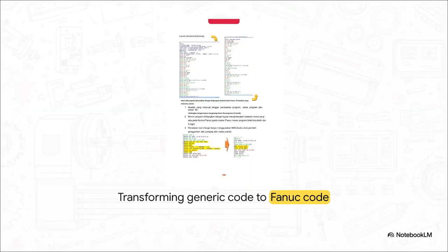Let's actually look at this in practice. First, take a look at the raw, generic output straight from Mastercam's post-processor. It is cluttered. You've got parenthetical comments, ridiculously long file names, and descriptive tool data that the machine's computer simply doesn't care about. And honestly, it might even choke on it. But then, look at our refined FANUC-ready code. We've completely stripped the header. We've isolated the tool calls down to just those essential M06 commands. This code is now lean, it's efficient, and it is perfectly formatted to guarantee a flawless, safe machining cycle without throwing any controller alarms.